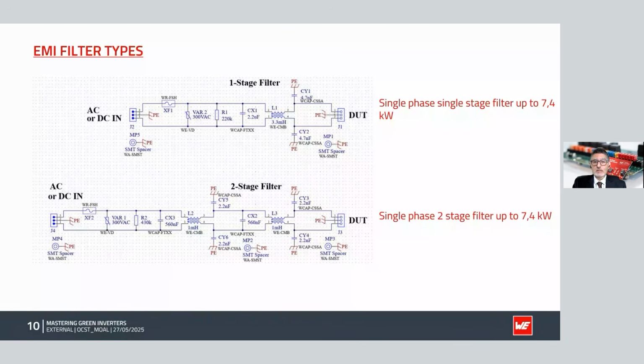This is very much reliant on the type of topology that you're switching and how clean your supply coming back is. One thing that is beautiful about this type of architecture, single or double stage, is, and maybe something that's missing as well, is where's the differential? I've talked about the common mode stage here. I've talked about a capacitor as a single 20 dBs per decade filter. Is that going to be sufficient? The nice thing and the beautiful thing about this is these common mode chokes also provide you with leakage inductance. So that also acts as a series L, if you want to call it that.